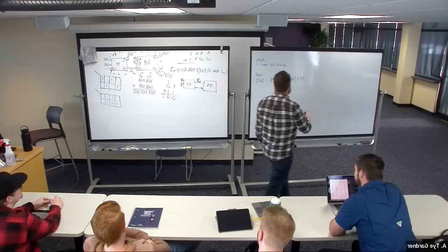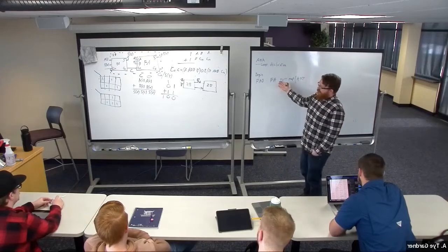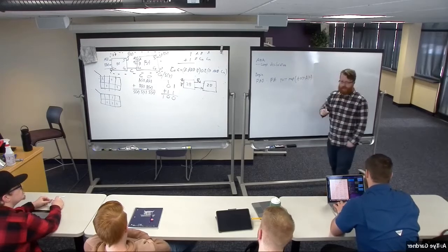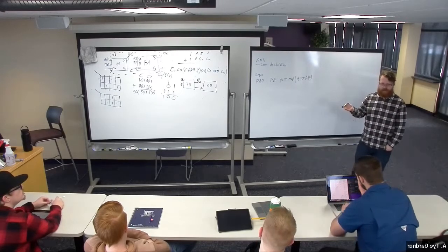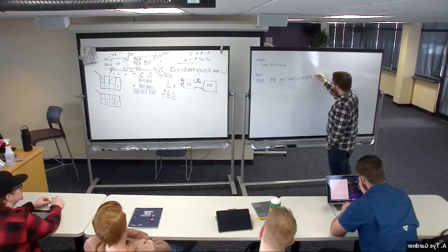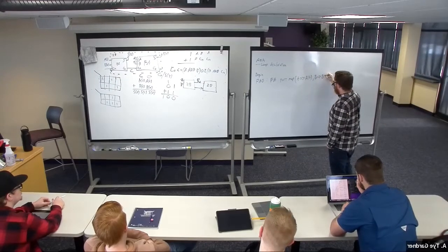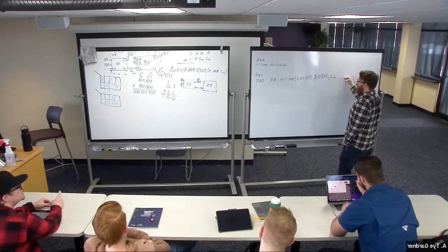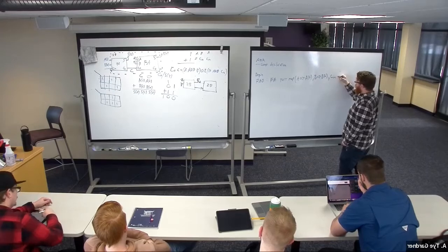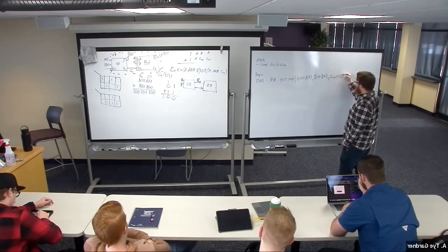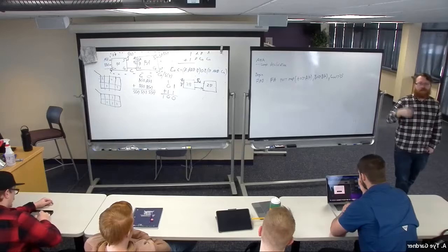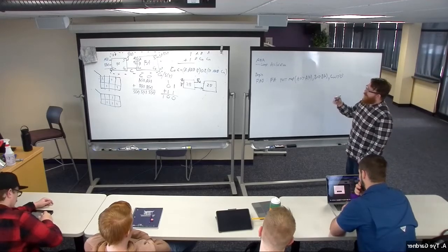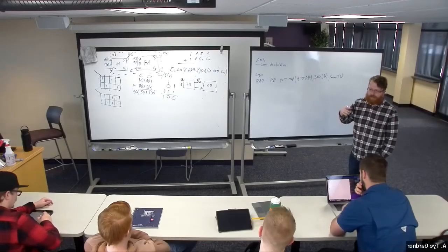So what I do is I say, well, my first full adder, A, gets mapped to the first bit of its input vector A. B gets mapped to B at 0. Cn, again, this is FA0, which is the leftmost one, gets mapped to 0. Now I've tied it to ground, which I've done. Well, that works if I'm trying to stop at the 2-bit adder, if I'm done.